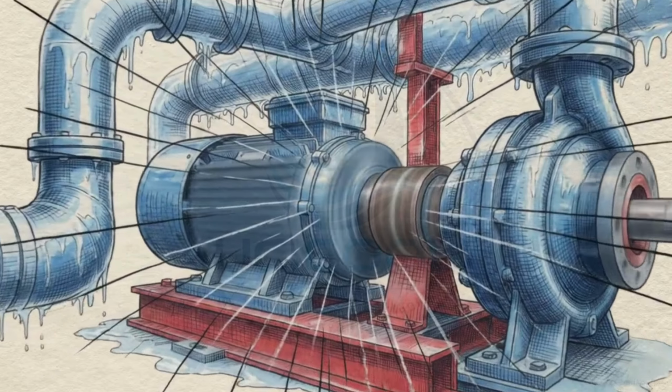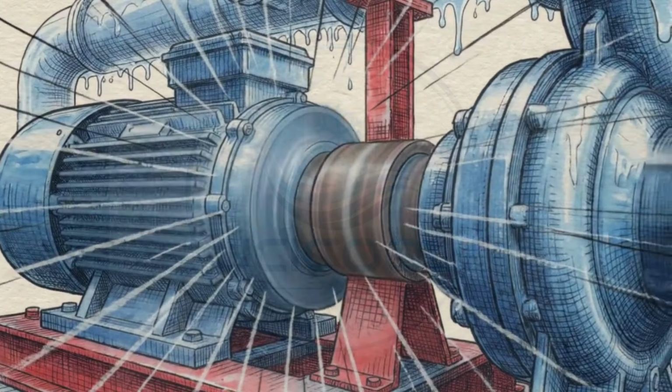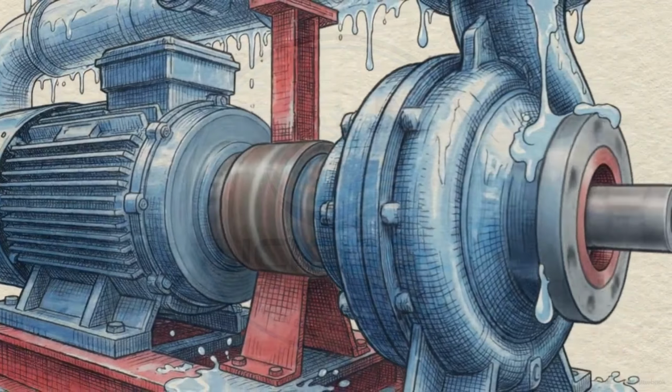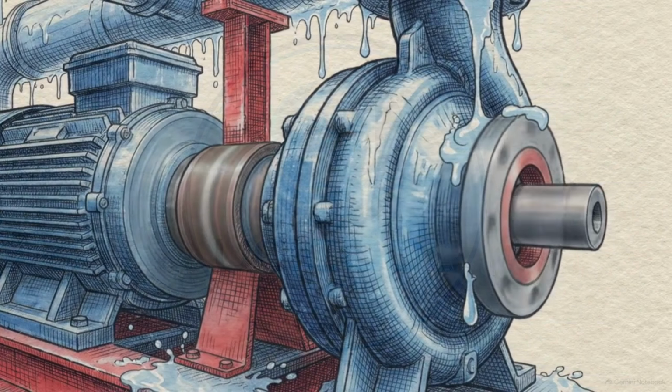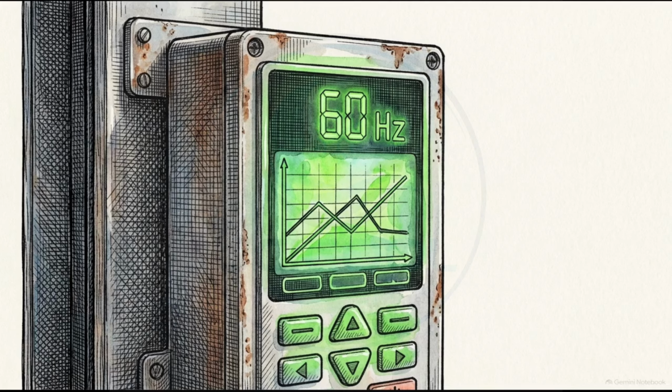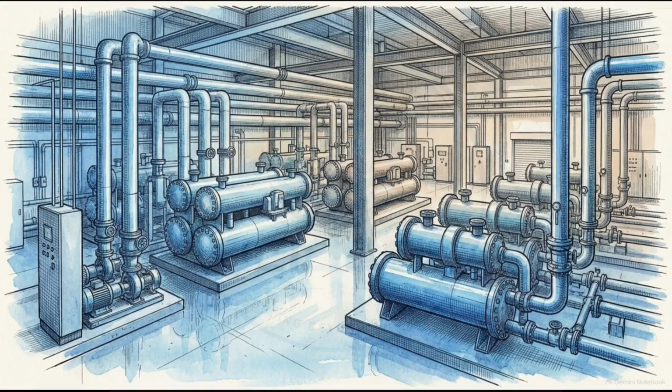The pump functions as a dynamic engine, modulating its mechanical output to track the shifting hydraulic requirements of the building loop. Mastering variable frequency control and accurately mapping the intersection of pump and system curves is the only way to extract the full designed capacity of a modern centralized chiller plant.